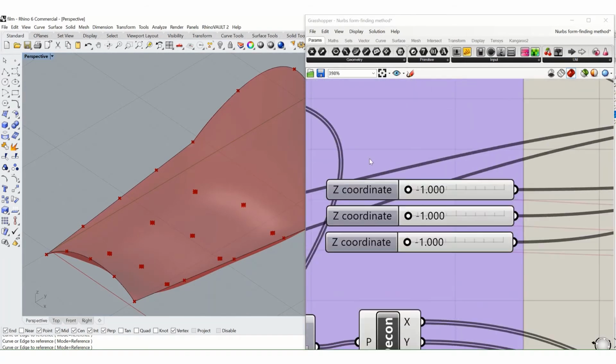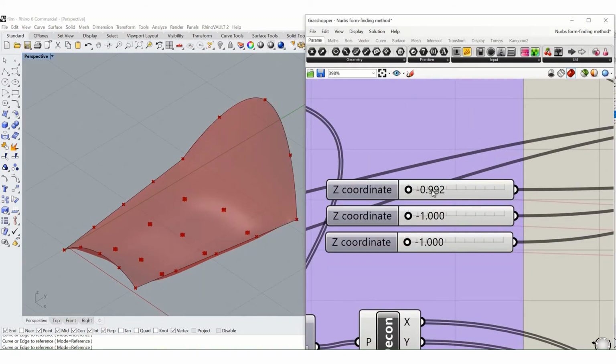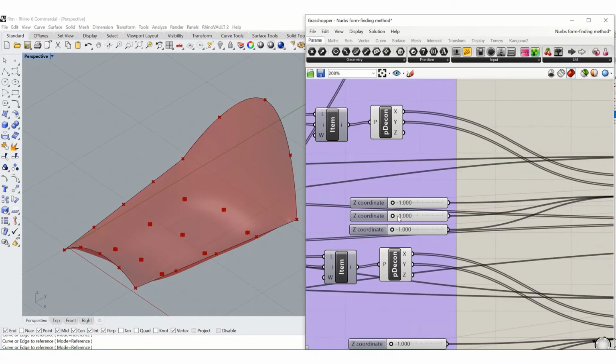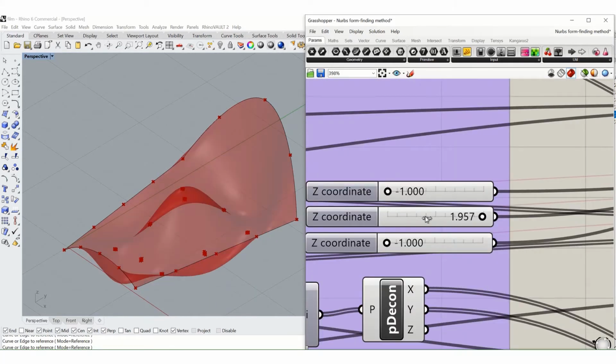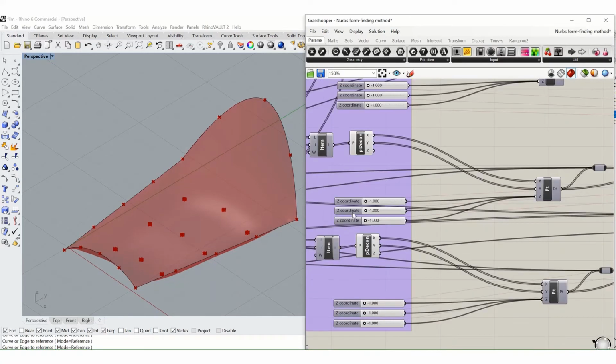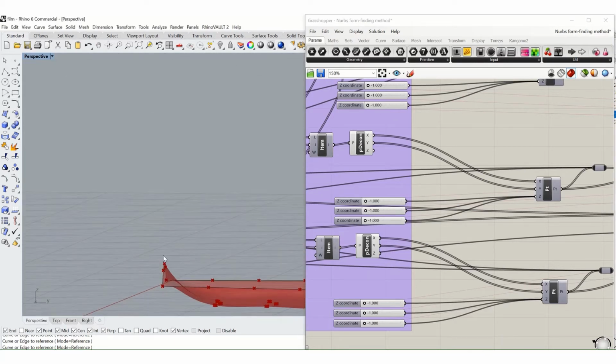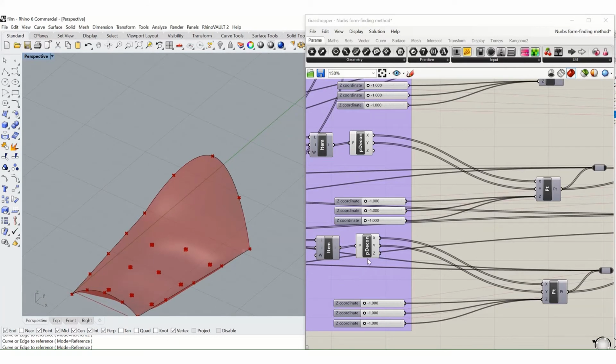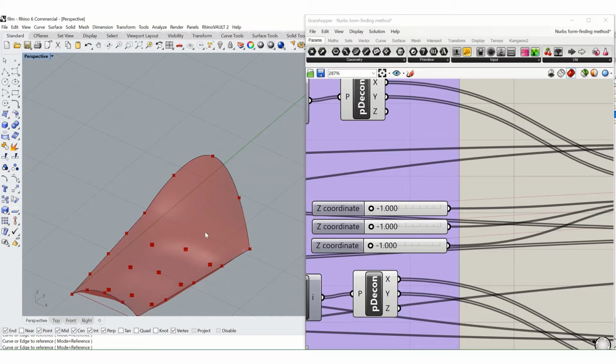So these are the variables object of my optimization algorithm. They are sliders here in Grasshopper. You can see how they move, alright? Under a certain range, the range defined for this variable must include the final solution. Right. Now the initial shape is completely independent, as in any form finding exercise. We'll just leave them here at a constant set value, but any initial shape is valid. So any initial value of the seed coordinate for this point is valid.